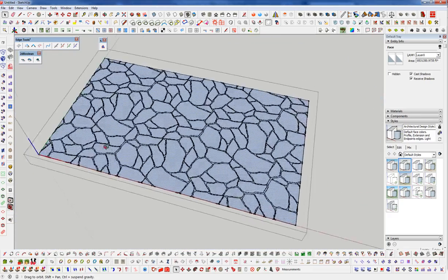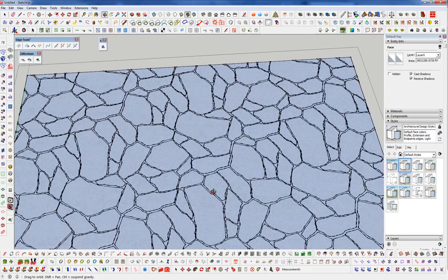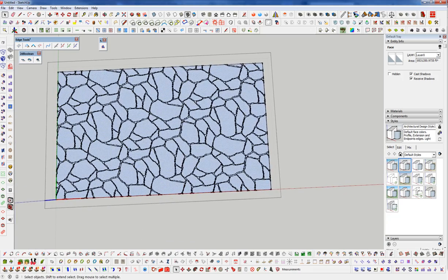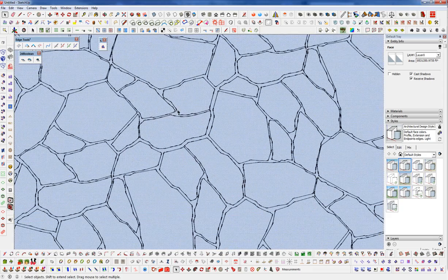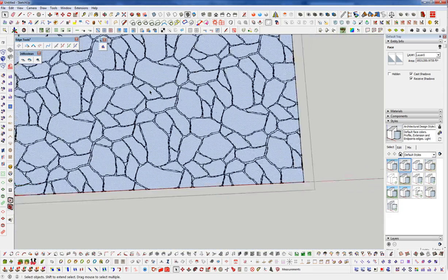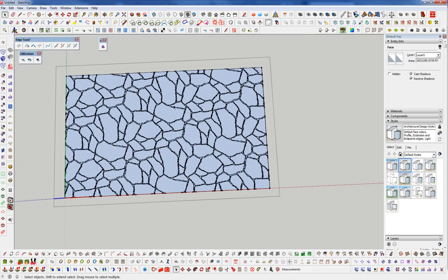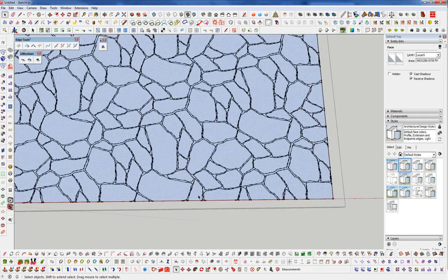Now if I wanted to go and use this as let's say some type of a walkway or wall, as a stone hatch even, this wouldn't work. I would need to close all of these, and that way I can go ahead and texture these. I can texture the mortar joint in the middle, and even do some things like 2D Boolean operations. I would need all of this to be tidied up and closed.